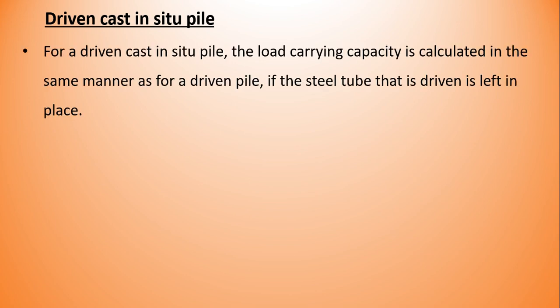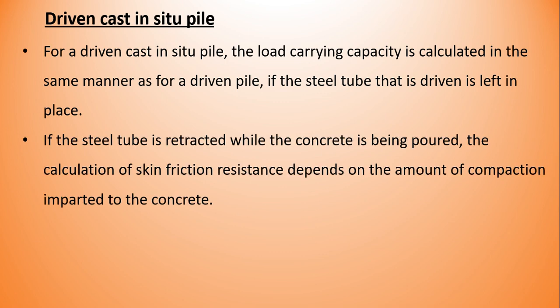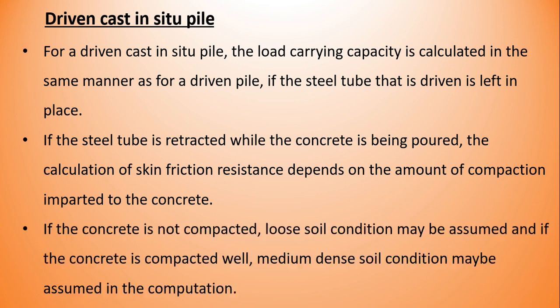Driven cast in situ pile. For a driven cast in situ pile, the load carrying capacity is calculated in the same manner as for a driven pile if the steel tube that is driven is left in place. If the steel tube is retracted while the concrete is being poured, the calculation of skin friction resistance depends on the amount of compaction imparted to the concrete.